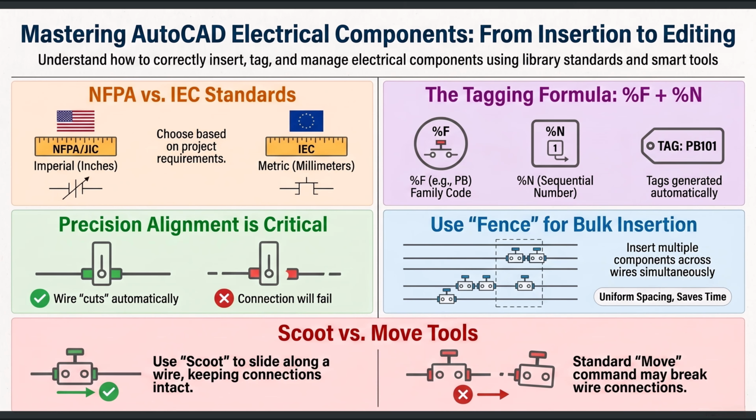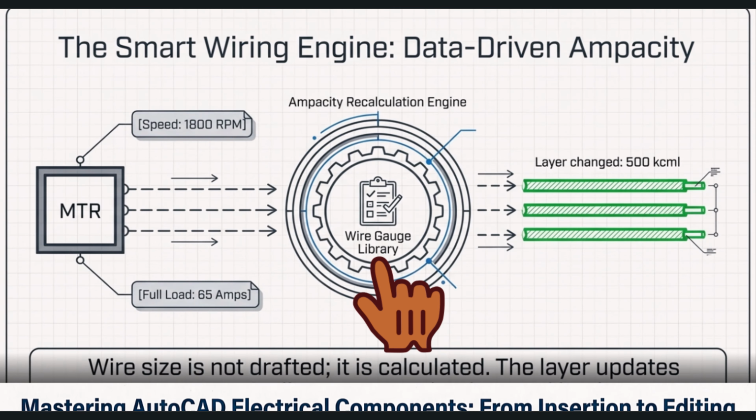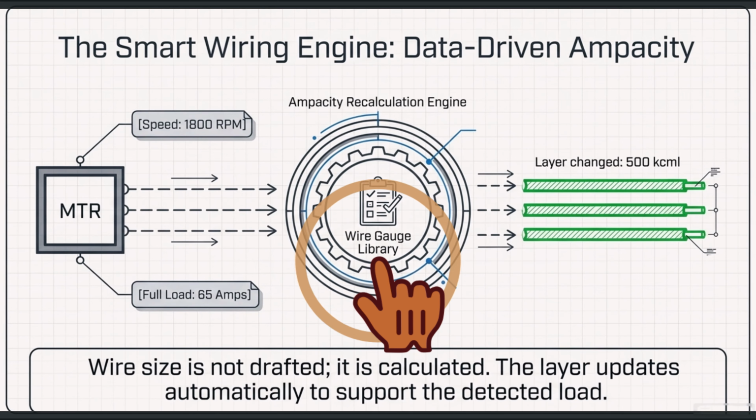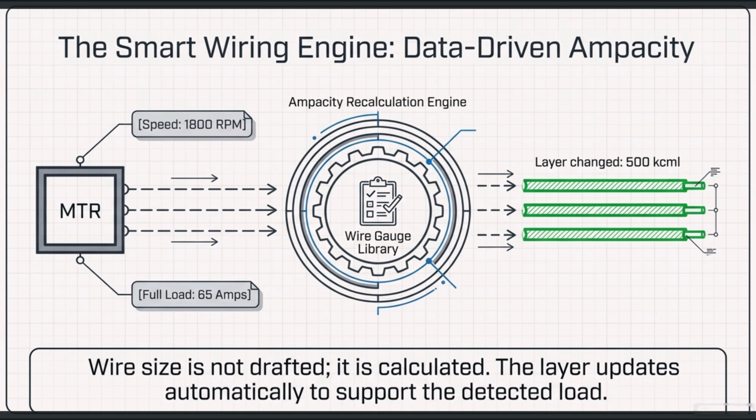But here's where it gets really interesting, because moving one part is easy, but handling the complex system physics is the real nightmare. Exactly. A schematic has to obey real-world constraints. The software acts as a real-time auditor, verifying electrical compatibility on the fly. Wait, really? By calculating component loads against wire gauges? You got it. If you try to push a massive load through a weak wire, it flags the mismatched ampacity right away, highlights it in red.